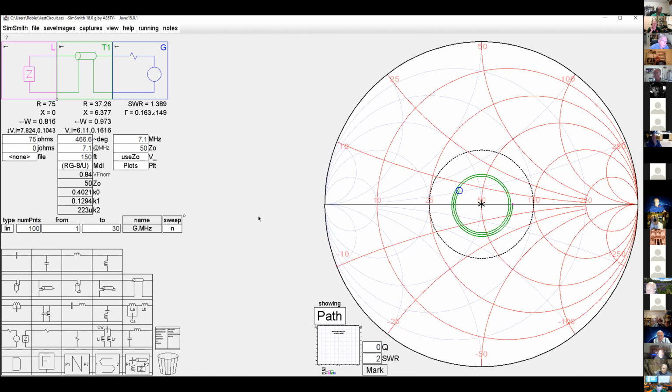Yeah, the other example would be if you have a piece of transmission line that's totally unmatched to either the rig or the antenna, and then you would start mapping impedances all over the place at one end of the transmission line or the other. That's right. Or if you have a segment of transmission line somewhere in between those two points that has a different impedance, that's another thing that can throw you for a loop.